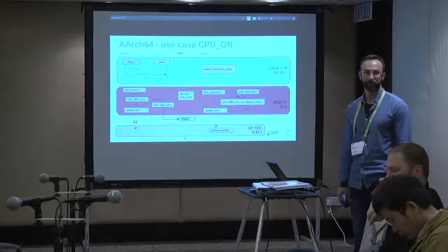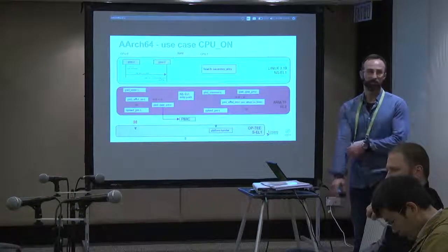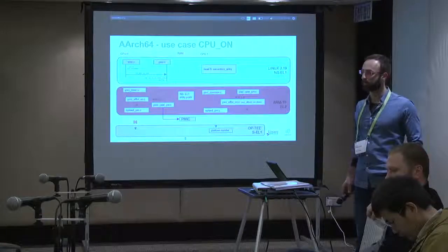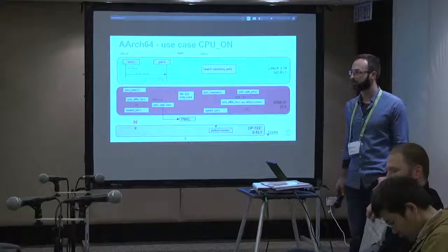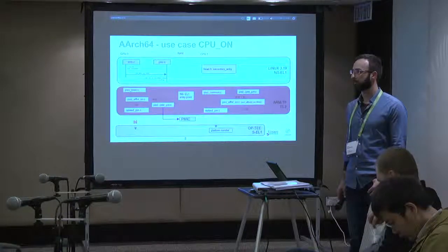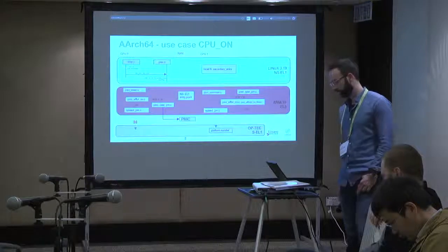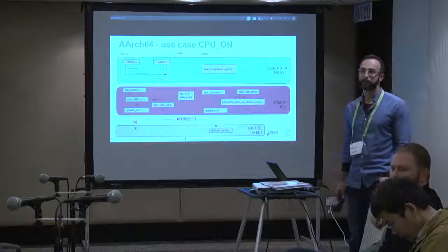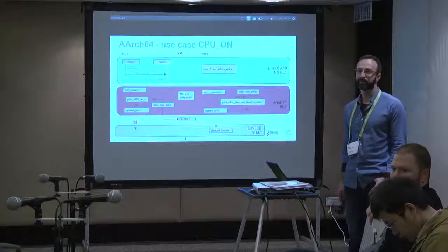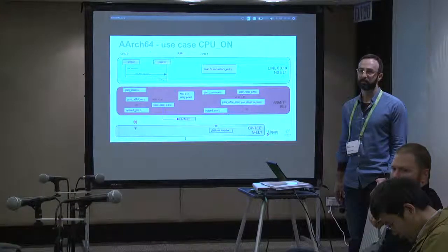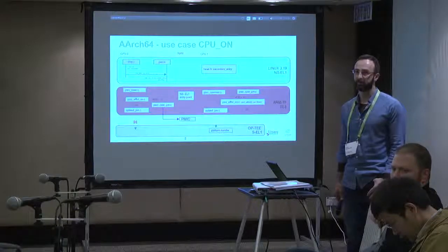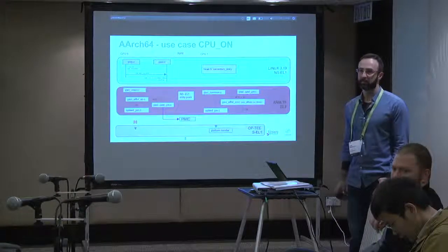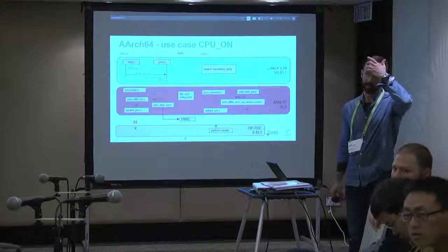So I guess what he's asking is, can we have a callback from the ARM Trusted Firmware, if the call actually happens to be an I2C, instead of writing the I2C driver on the Trusted Firmware side, to have a callback into the kernel and then come back somehow? Right? Yeah. And it's not just the callback. You need to deal with potentially contention between the trusted firmware and the rest of the OS if there's anything else on the same bus.